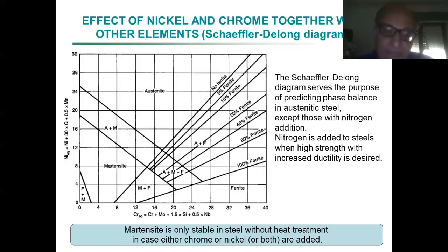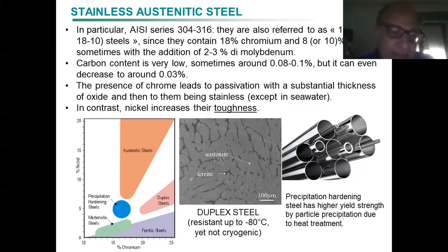As I already mentioned, martensite can be present. There is not much difference with what we have seen last time. It's more precise, and these commercial categories are not indicated. So these are commercial categories: precipitation hardening and duplex steel. But it's important to know them because in practice they correspond to physical reasons: the precipitation of particles and the presence of austenite and ferrite.